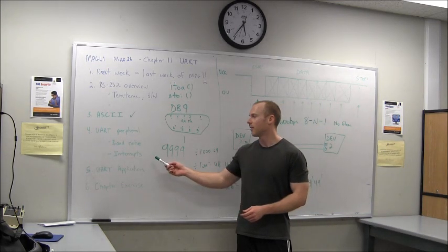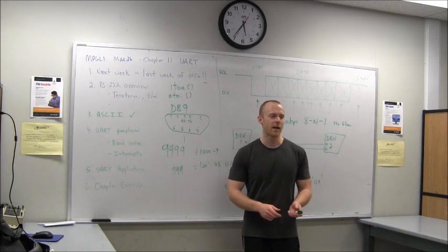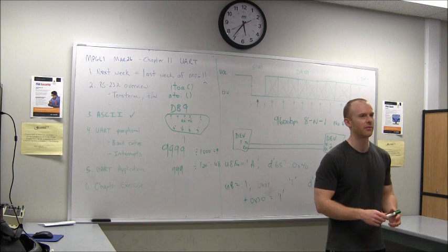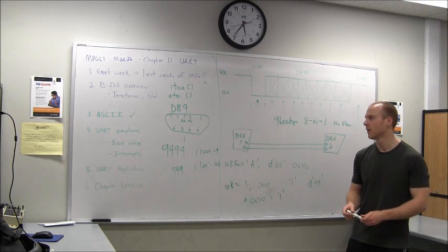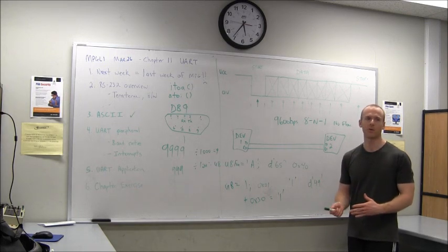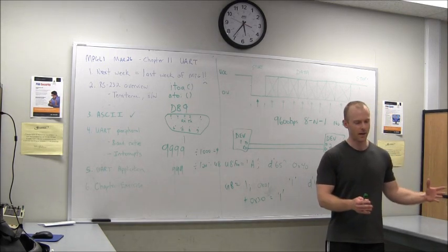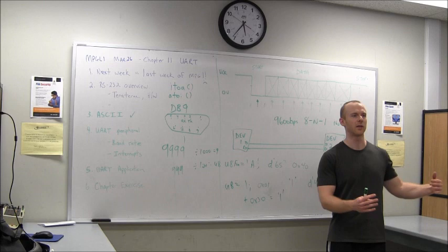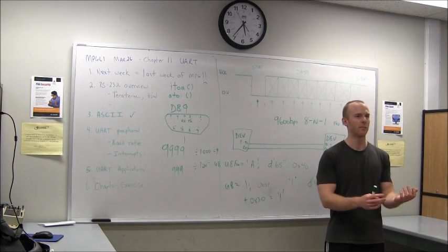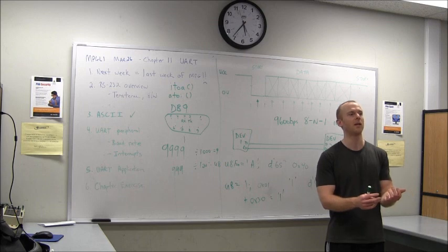And other than figuring out what interrupts to have, the UART has within it 4 or 5 different sources of interrupts, so you can do different things. There are some built-in buffers on this peripheral, which is nice. So in hardware, there are hardware buffers that can read in a bunch of characters, and so you don't have to respond to every single byte coming in immediately.